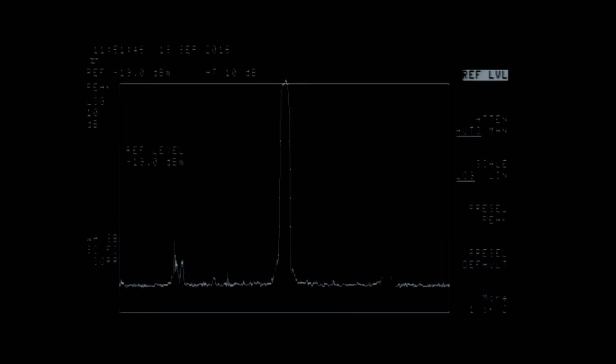And this is with the DVB-S software operating at 1 megasymbol per second. There's a 50 meg sweep across the spectrum analyzer, so you should always have filtering after the output of the DATV Express.